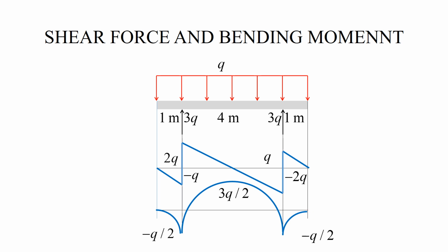Next, we need to talk about analyzing the cross-section. We begin with identifying the centroid of the cross-section, and to this end, we identify the flange with the first subdomain and the web with the second subdomain.